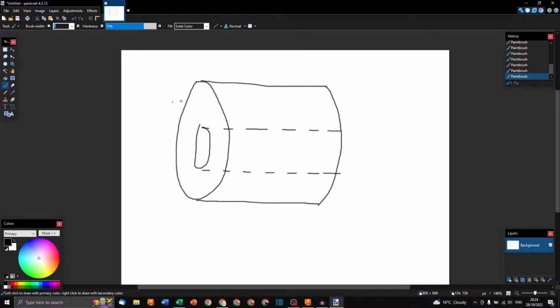So extruding is taking a 2D surface and pulling it out into the third dimension, like this. So for a wheel, the ideal surface to create a sketch of is going to be this face right here, because it's a simple 2D face that you can extrude into the volume.